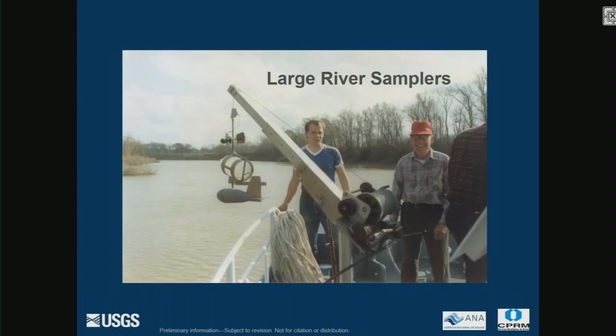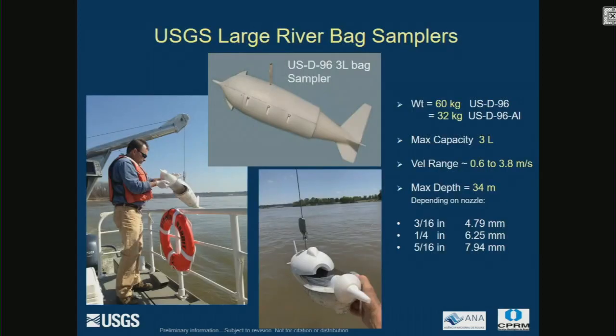So this is a current meter, the way that this was done in the past. As it was lowered down, the current meter was active, and you could hear the clicks through the line, get the velocity where the sampler is, and then you would be able to measure the velocity as you're going up and down. There was no power reel here. It was power, but it's one speed only. So that was a holdback. This actually, I think, is a hydraulic type reel where they were able to change the speed of that motor and that reel to some extent. And some of those still exist.